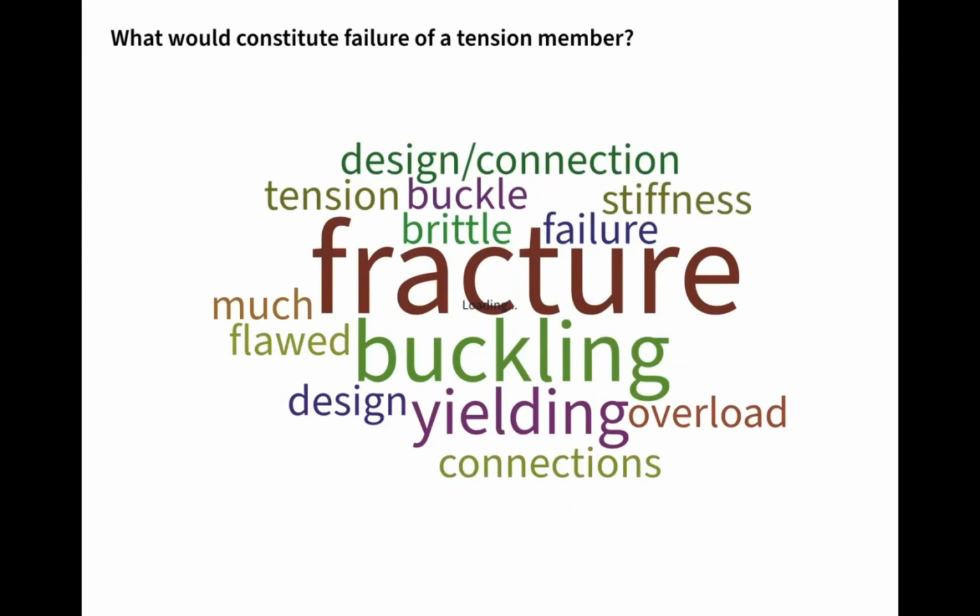Stiffness is important, and we'll see that one of the primary drivers for why we're going to check the yielding of a brace is because once a brace starts to yield, it's no longer able to provide a stiff response that can prevent the building from tipping over sideways. And so once something starts to yield, the stiffness goes way down, and we start to get gravity loads more or less taking the structure down with it. And so that's an important thing.